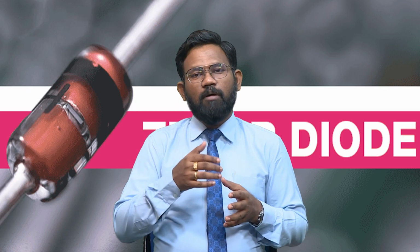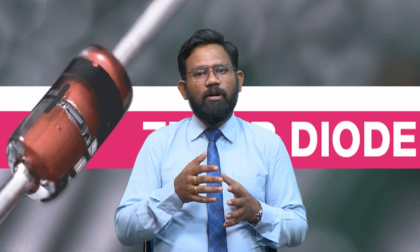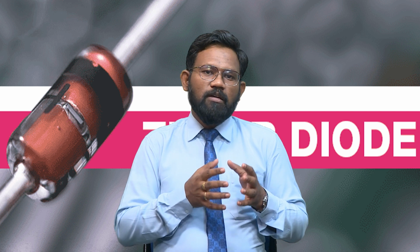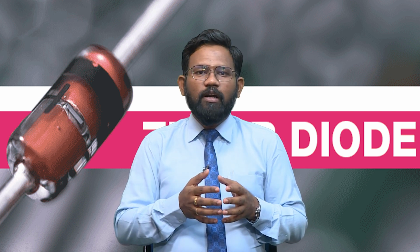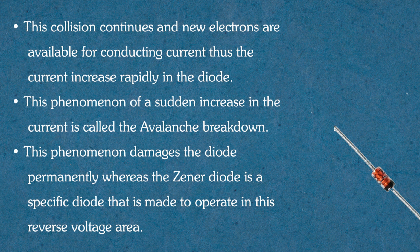The reason for the drastic and sharp increase in current is the collision process and the development of new electrons. More and more electrons become available, and due to this the current goes on increasing in the reverse direction. This phenomenon of a sudden increase in current is called the avalanche breakdown.